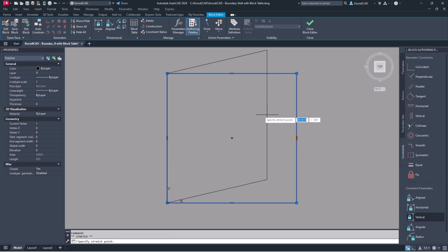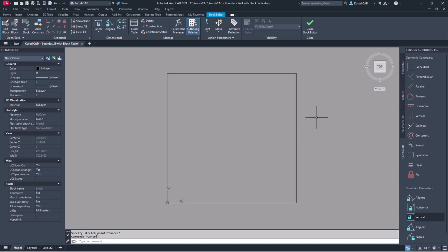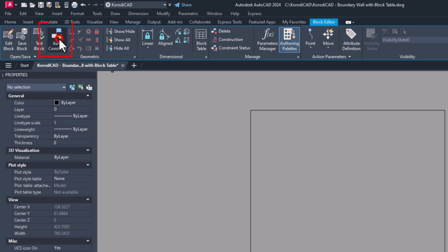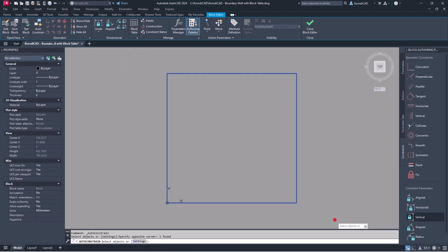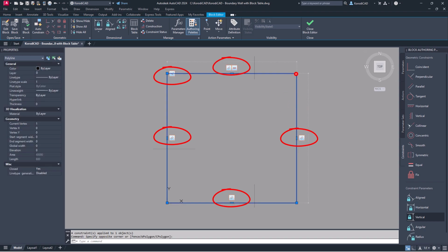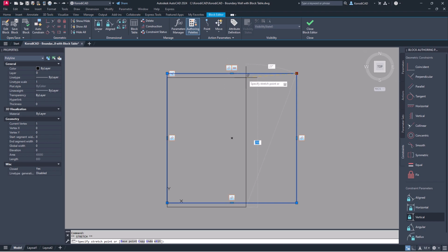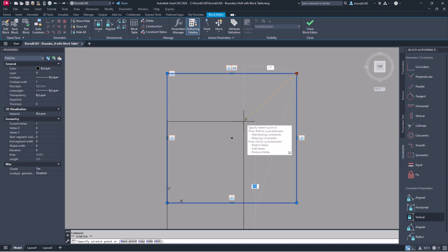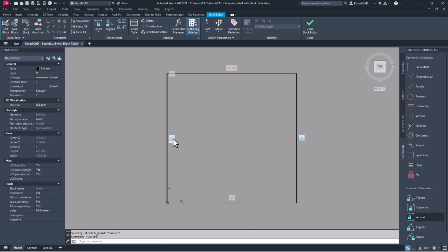The problem with this is that it would take a lot of parameters to get the sides to hold the rectangle. Use auto-constrain to force the object to keep right angles and parallels. These icons show what constraints have been created. The parallels and right angles in the object are preserved under all circumstances. If you hover the mouse over the icon, it will show you the element of the object for which you have created a constraint.